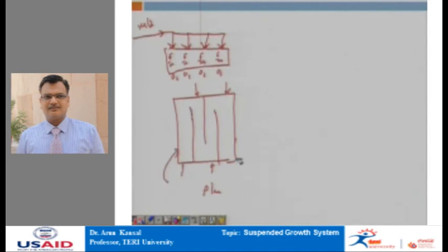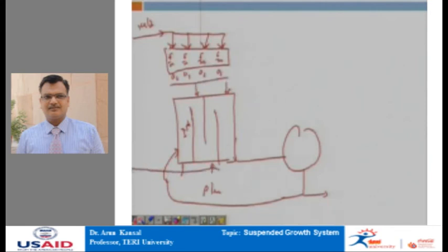After this, the wastewater goes to the secondary settling tank, from where we are returning the sludge, and this is returned to the first unit of the step aeration. So, return activated sludge enters the first step of the aeration tank along with a portion of the settled wastewater. Here the piping is so arranged that an increment of wastewater is introduced in the aeration tank at each step. This is done through the various piping arrangements.